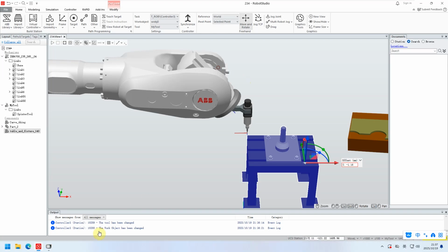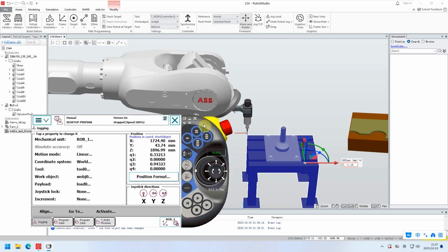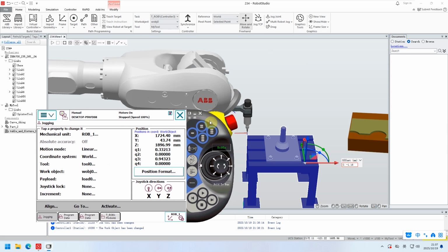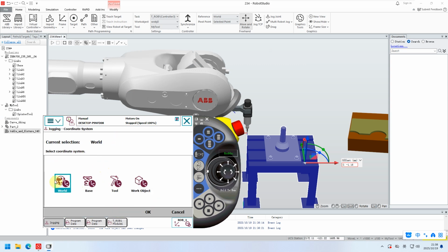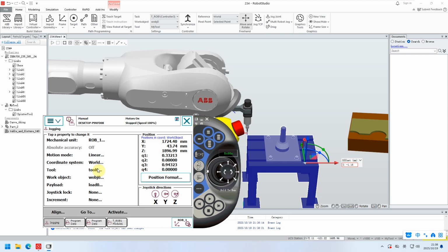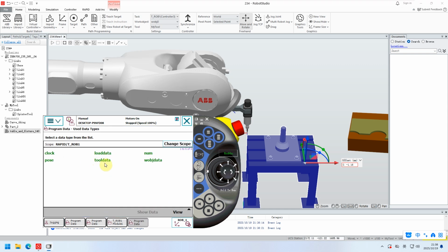Today's video, I'm gonna tell you how to configure setup tool coordination in ABB Robot. So let's begin the topics. First, you have to jog in. You choose the word, okay, and the tool. You choose the default one, and you can set up a new tool data.